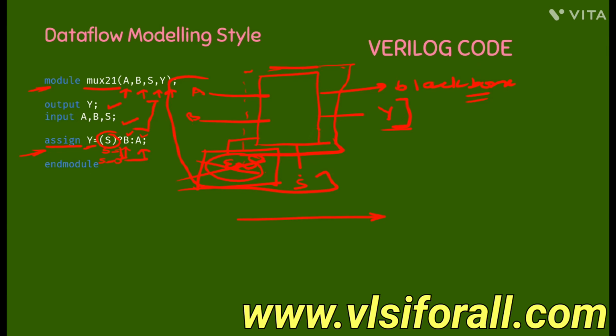So this is the very simple example of how to use the conditional assignment statement and how to exploit the functionality of true and false in the select statement for a simple 2:1 multiplexer. Followed by this, we simply end the module.